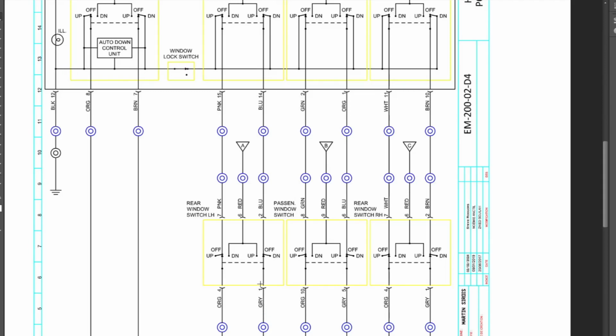And let's take a look at the other side. As you probably guessed, that's up here, through this side of the switch, and to ground. You can test this power window in a Hyundai exactly the same effectively as you can this Chrysler Concorde power seat. Now let's move over to a power door lock for a 2007 Chevy Cobalt.